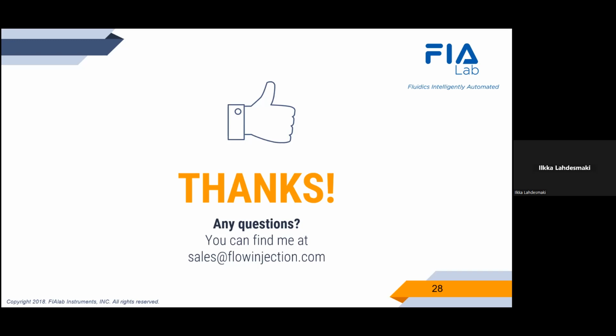The way we've addressed those is, first of all, it helps that FIA Lab uses so-called array detectors for our color measurements, where we are able to utilize other wavelengths than the wavelength where we're monitoring to put in place background correction protocols that attenuate fluctuations caused by brackish matrices.